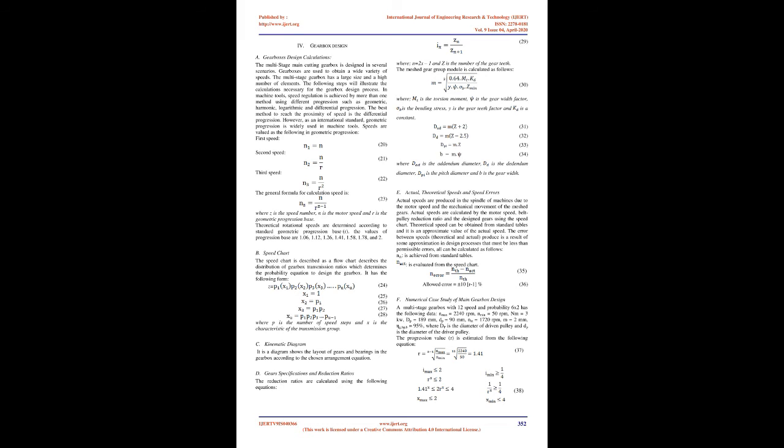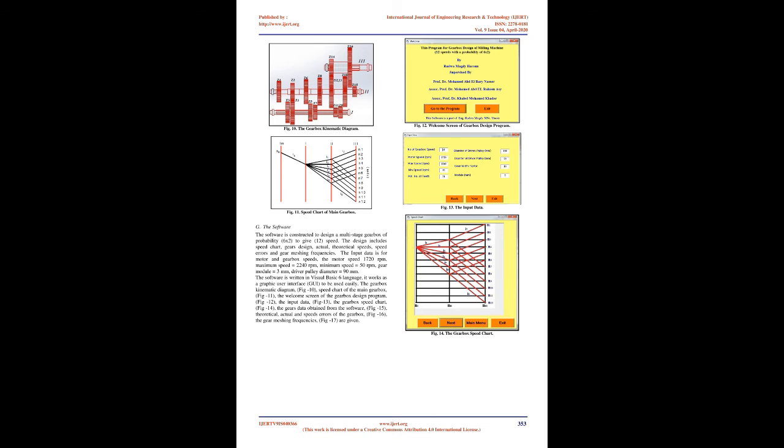Harmonic response analysis. By selecting the FRF analysis option, the integrated harmonic analysis tool opens. The frequency response function at X, Y, and Z direction of the original and the four modifications of the milling machine column are obtained. Many risky effects on the machine tools can be avoided reliant on the harmonic analysis, which depends on vibration analysis. Moreover, the frequency response function, FRF, can be considered as an effective design tool to help the designer. Therefore, the designer can depend on the FRF to provide him with the necessary details about the frequency of the high response and the time of its occurrence.